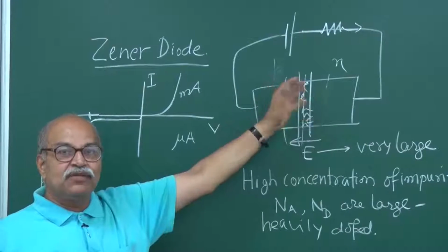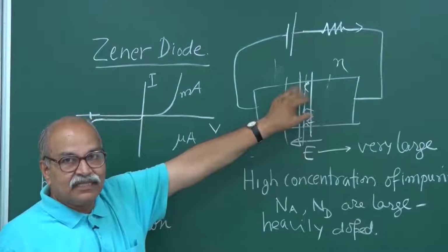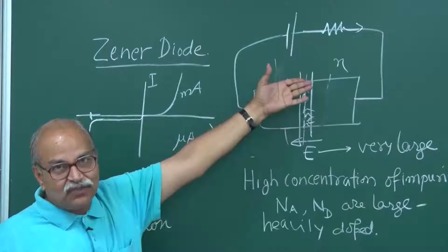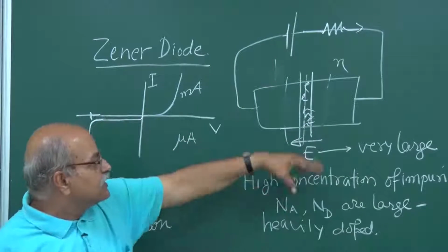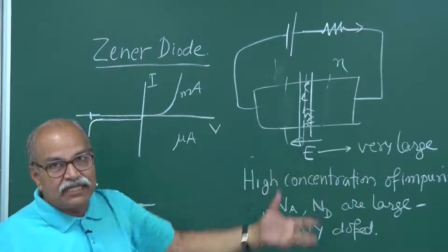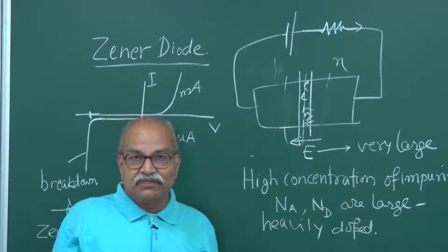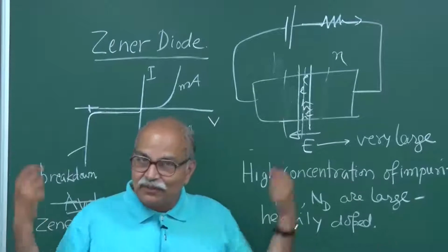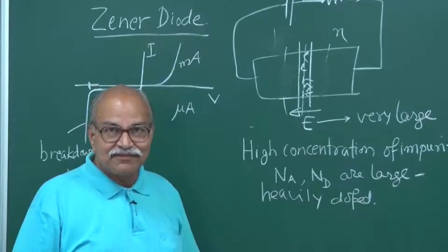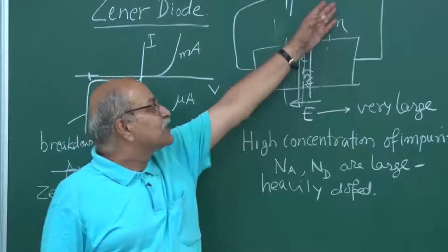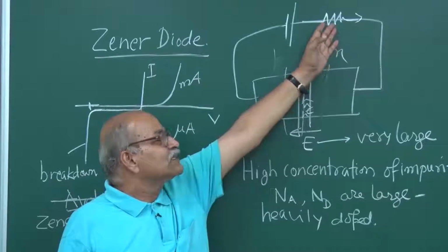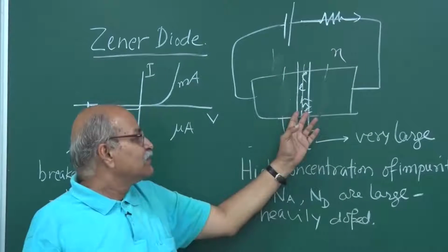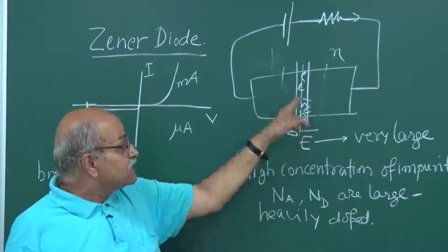The moment it becomes 2 volts, you have all this process starting, and then it cannot increase beyond 2 volts, because at 2 volts itself, if you try to increase, the current will increase very high, and if you put really more than that 2 volts, then the whole thing can get burnt, right? So you must put a resistor here, so that any extra voltage drops here and here, and the diode remains at the voltage for which it is created.